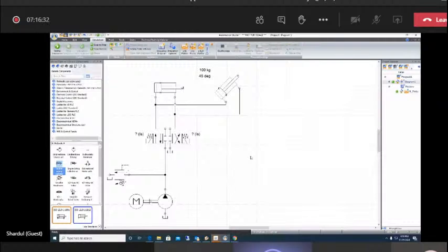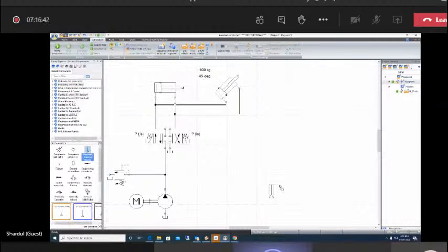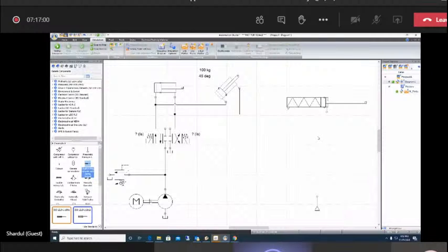that is pneumatics that we have. So for example, in pneumatics also we have the libraries configured like in hydraulics. So you can take a pneumatic pressure source. Now obviously in pneumatics you need compressed air instead of fluid. So you have a pneumatic pressure source or a compressor that you can take. You can take a single acting cylinder, and you can also take an electrically controlled directional control valve. I'll just make the connections.